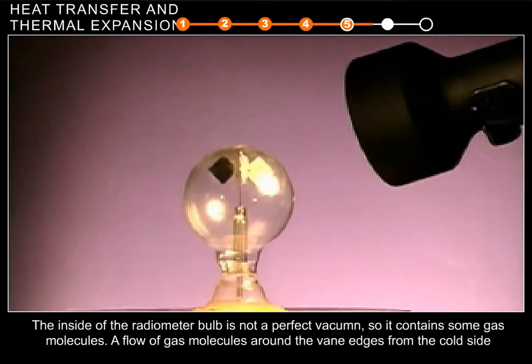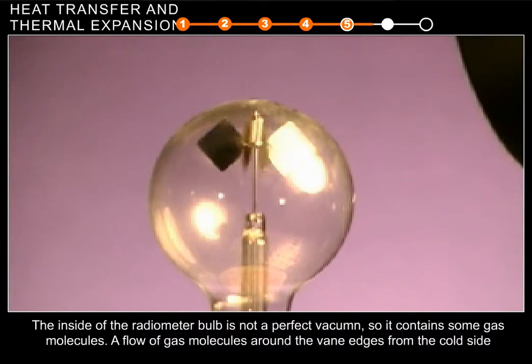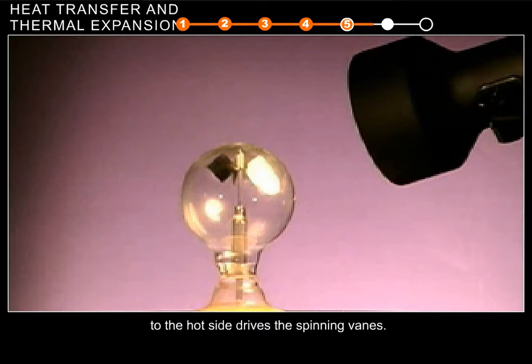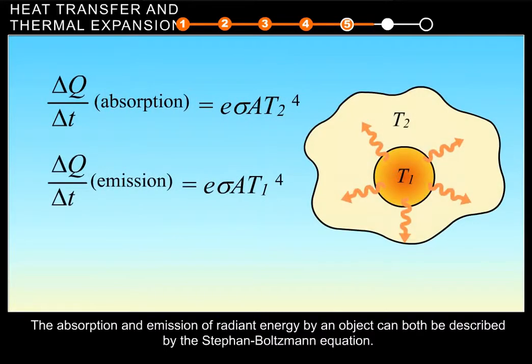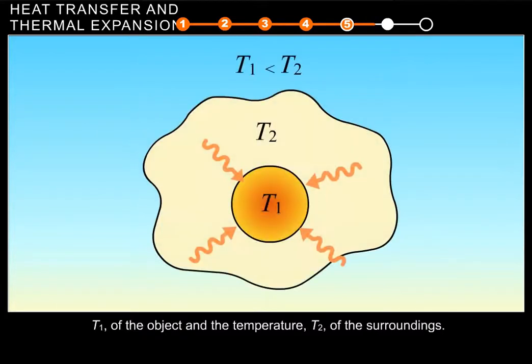The inside of the radiometer bulb is not a perfect vacuum, so it contains some gas molecules. A flow of gas molecules around the vane edges from the cold side to the hot side drives the spinning vanes. The absorption and emission of radiant energy by an object can both be described by the Stefan-Boltzmann equation. If an object and its surroundings are not in thermal equilibrium, then there will be a net flow of radiant energy which depends upon the temperature, T1, of the object and the temperature, T2, of the surroundings.